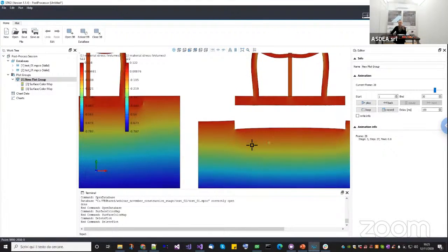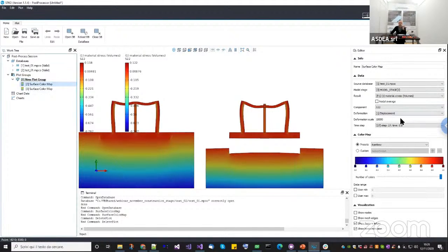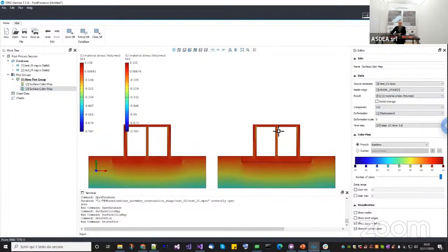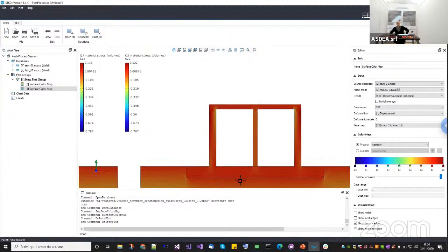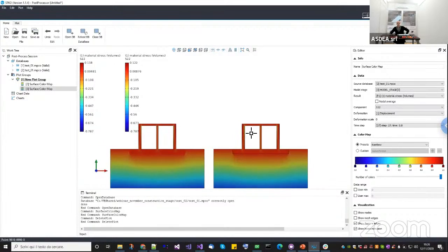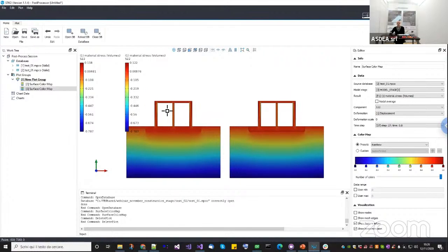So the only problem is that visually you see a gap between them, but it's not a problem because, remember that you're using small displacement assumption, so you can actually visualize it as a 0 deformation, and you will see no difference here. What you need to do in a small displacement analysis is just to take care of the stresses. Okay. So why is this version here better than this one? Well, because this one has many drawbacks, as I've shown before.